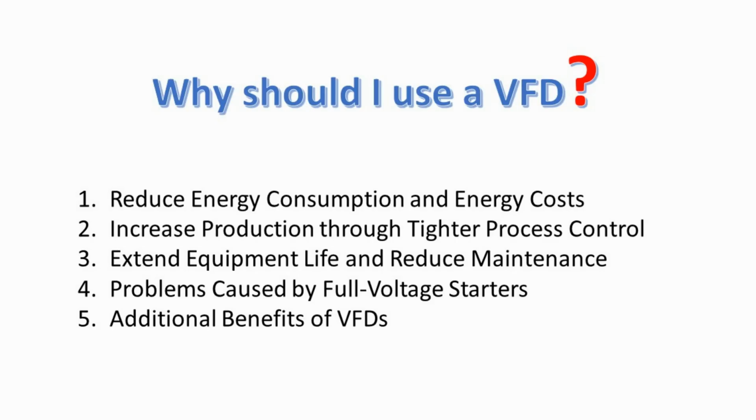After studying about VFD, the question that comes to mind is, why should I use a VFD? The answer to this question is as follows. Number 1, if you have an application that does not need to be run at full speed, then you can cut down energy costs by controlling the motor with a variable frequency drive. VFDs allow you to match the speed of the motor-driven equipment to the load requirement. There is no other method of AC electric motor control that allows you to accomplish this. We can save energy by controlling the speed of a pump rather than controlling flow through use of throttling valves. Energy savings can be substantial.